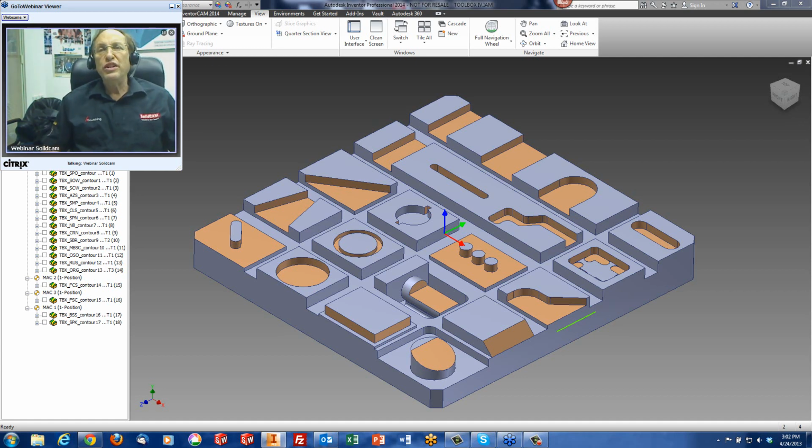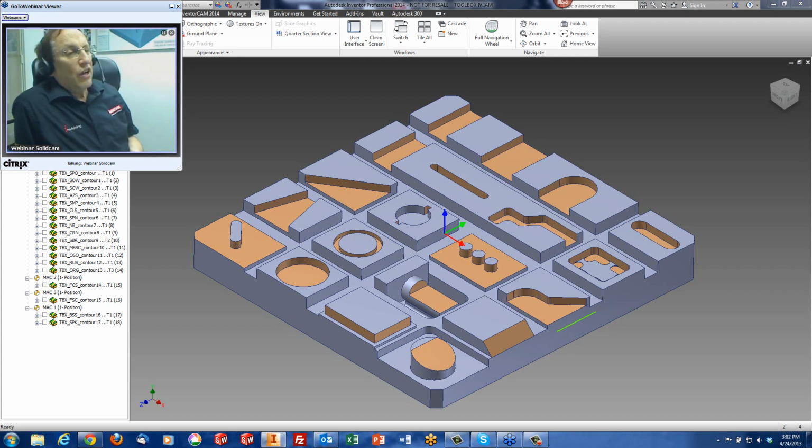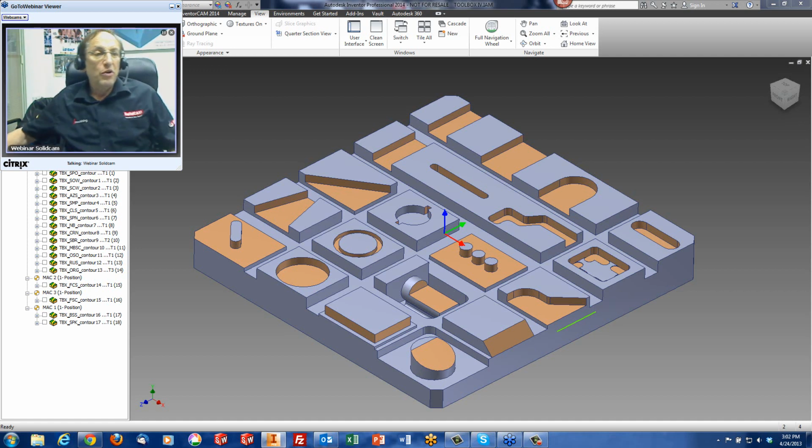Just like you have on machines, you have canned programs, let's say for drilling or sometimes pockets even, where all you do is just give it a shape and the machine itself gives out the exact moves. The same thing we have inside the ToolBox itself. You pick the specific type of operations you want, and it'll automatically give you the exact tool path that you need for that particular operation.